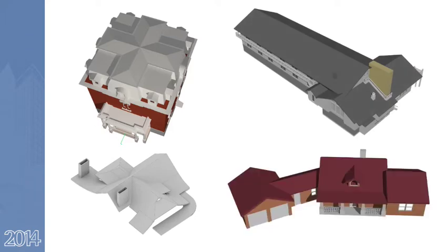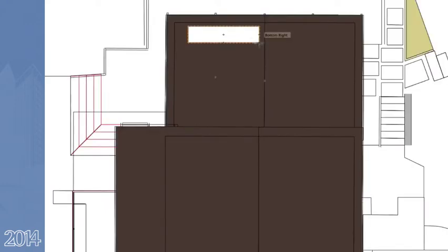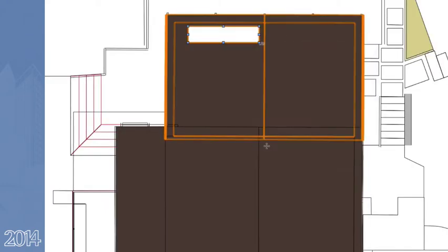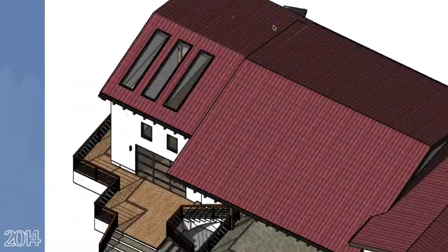We've improved the roof tool in 2014 with a few new capabilities that'll make working with roof faces and objects easier than ever. To start, you can now edit the shape of a roof object by using the Clip Surface command or the Clip tool. Once edited, the roof object remains an intelligent building object and retains its information.